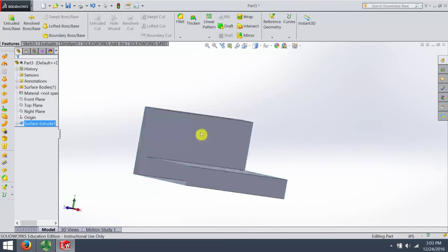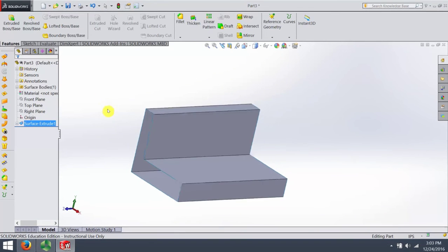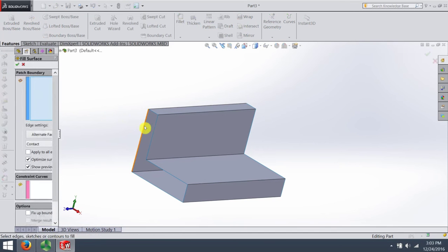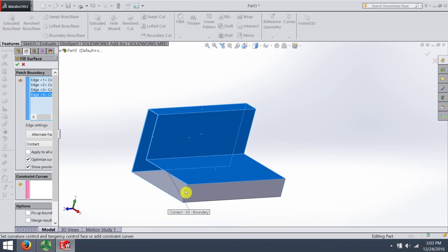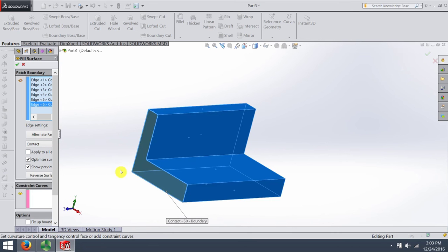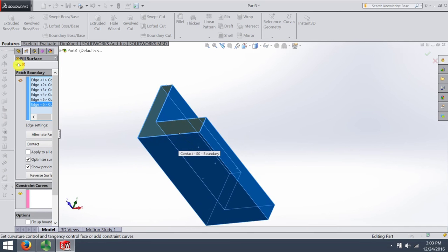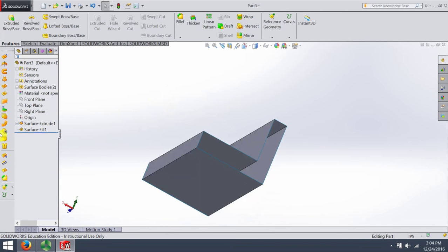It's really a bunch of surfaces. So now we want to cap those ends off. You already know how to do that. We'll go over here, grab that surface fill, grab those edges. I'm not remembering where it is right this second, but there is a way of having it just sort of follow this chain around. Right now I'll just grab each of these edges that defines the boundary of that end. There's our ghost surface, our preview. He's ready to go. Do that same thing again.